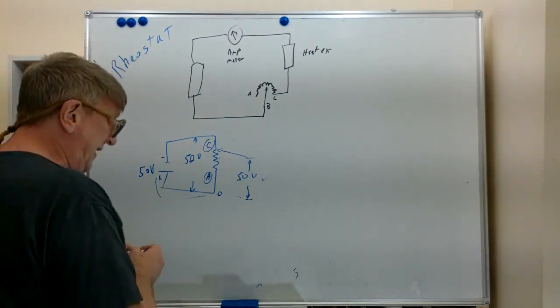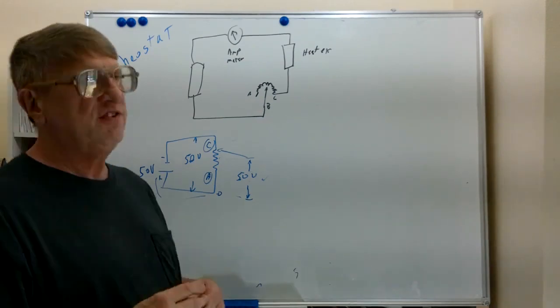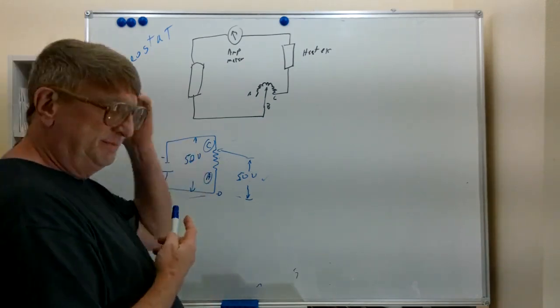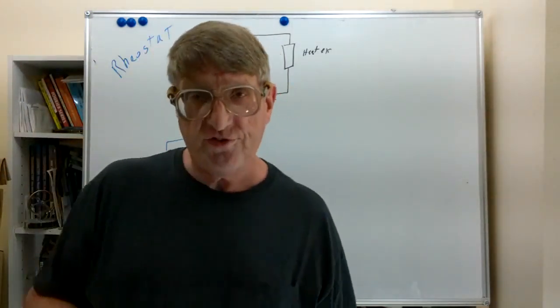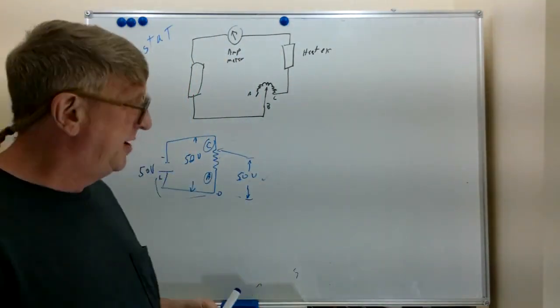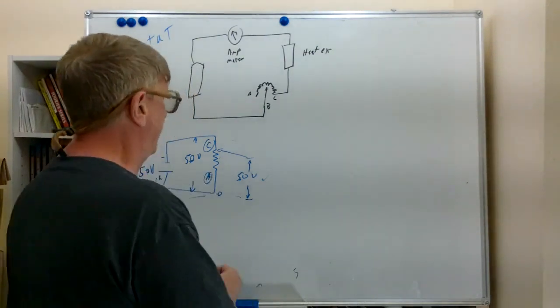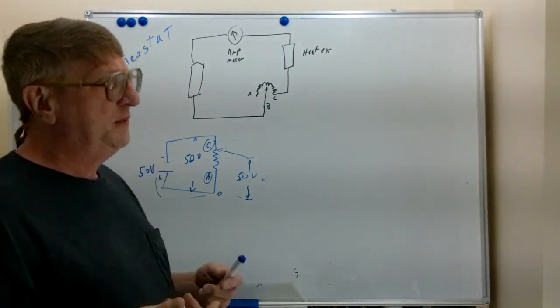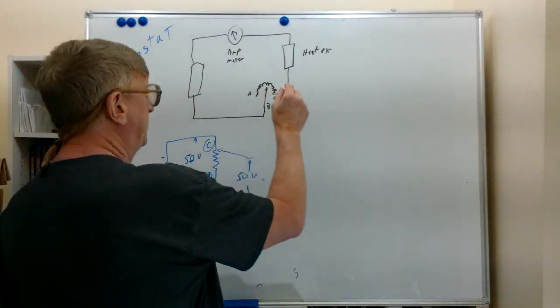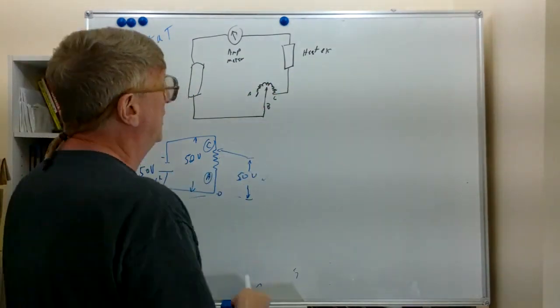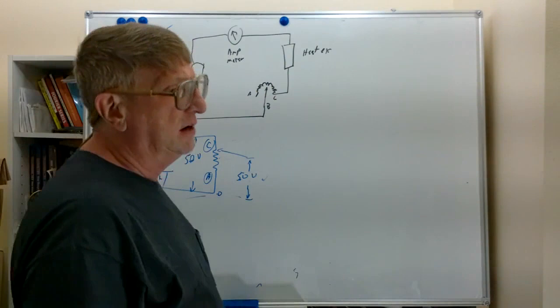Now, we might, in some case, use a potentiometer as a rheostat. As an example, potentiometers aren't designed to handle high current like rheostats, which are typically wire wound, like we needed for controlling this heater.